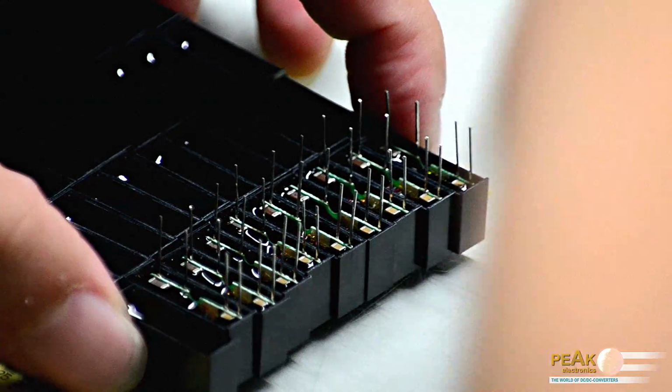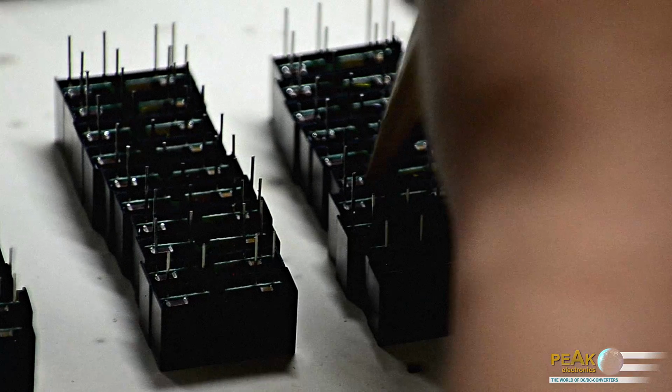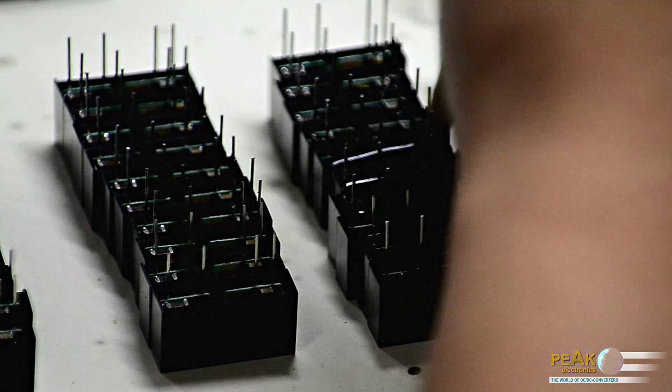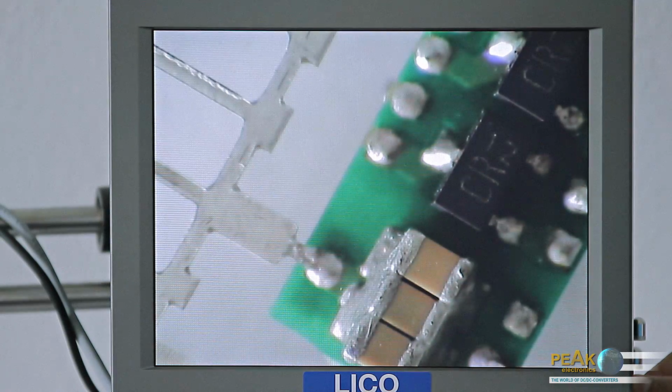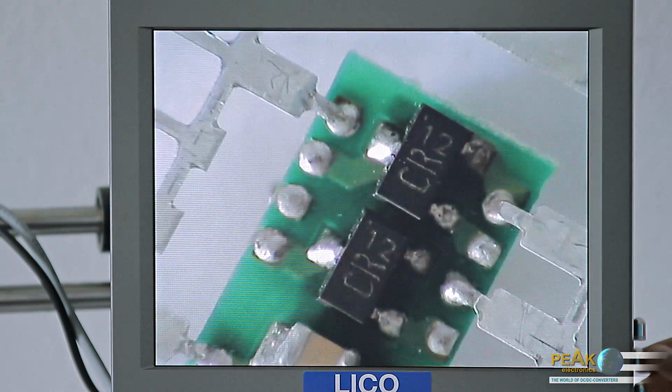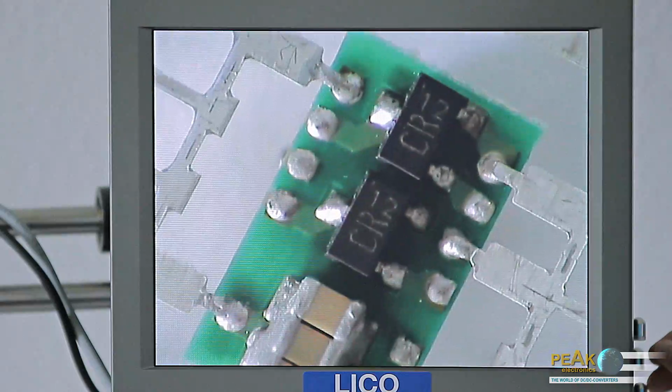Vibration and shock. Potted converters have a high level of resistance to mechanical stresses. In most industrial applications, at the most, care must be taken to make good solder points when assembling the converter in the application. Where high demands are made, a system test is unavoidable. The solder joint strength can be increased by an additional screw-mounted plate, clamp or spring clip.